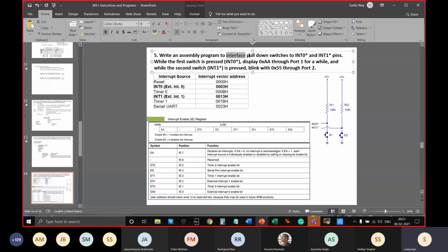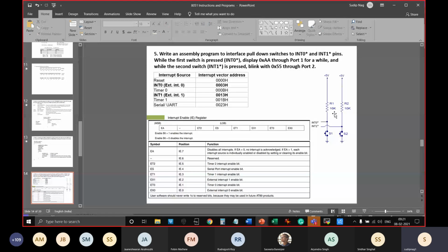This pull-up resistor is connected to the VCC supply, and this VCC may be 3.3 or 1.8 V depending on the technology of the microcontroller you are using. In this example it is 5 V, because it is the traditional 8051. The middle terminal is connected to port 3.2 or 3.3, depending on which INT.